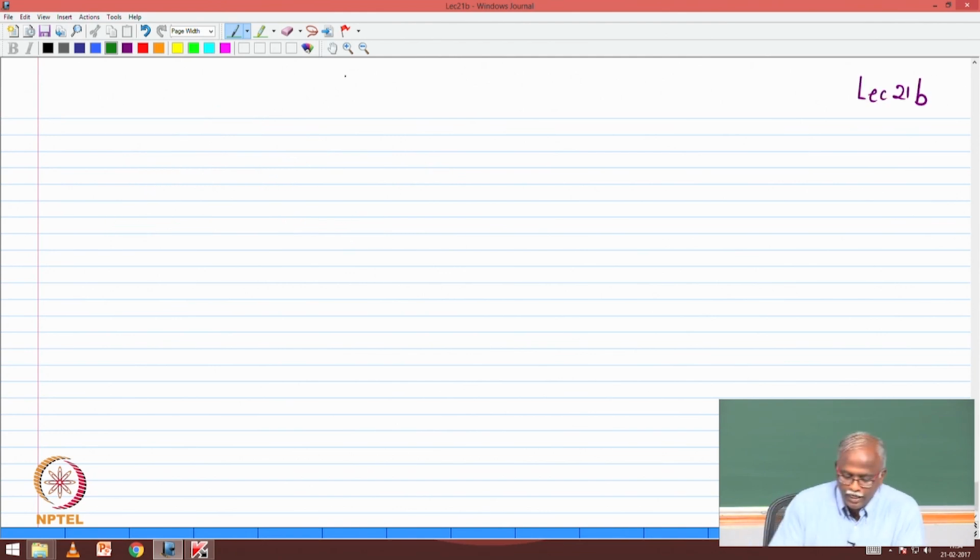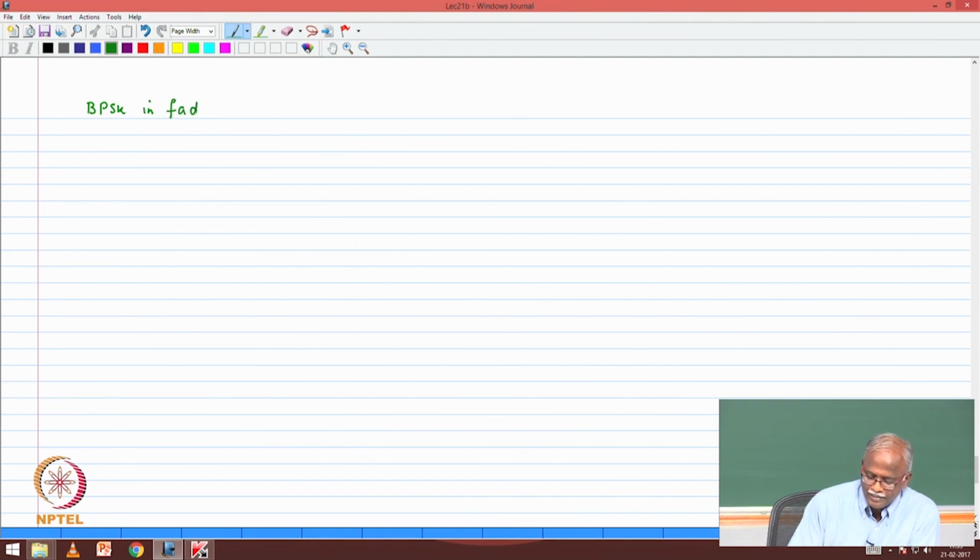Okay, so now what I would like to do is address the bit error rate probability of BPSK. Having done one, the other can't be too difficult, right? So obviously you should be able to try this one out. So the expression for this probability of error will be integral 0 to infinity. The Q function I will not write in terms of alpha, I will write it in terms of gamma, root 2 gamma, and the PDF 1 by gamma e power minus gamma by gamma d gamma.